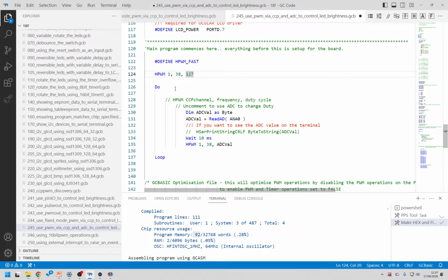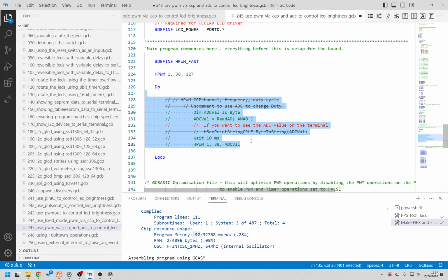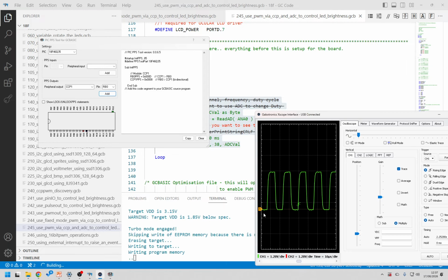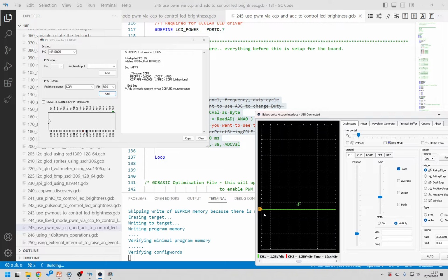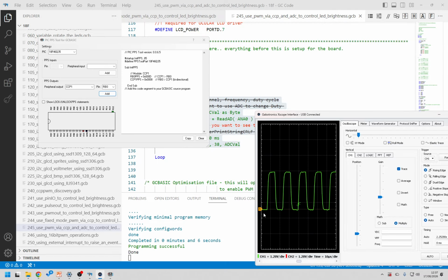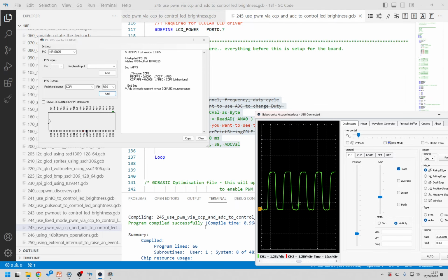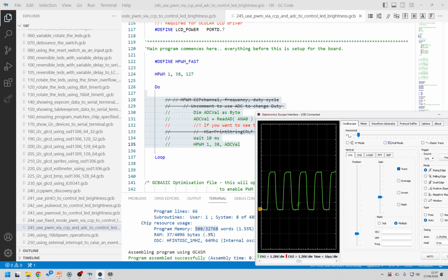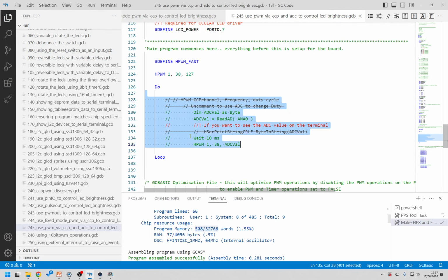So if I take all this code here and just comment it out for a minute, program it, and we'll go back to the oscilloscope. There's the oscilloscope. We will see the same signal. However, the size of the code to get to that point has grown to 500 words, because you can change the duty and the frequency because it recalculates everything. And so one does it in a script which gives you 2 constants that control it, and this is in assembly. So let's have a look.